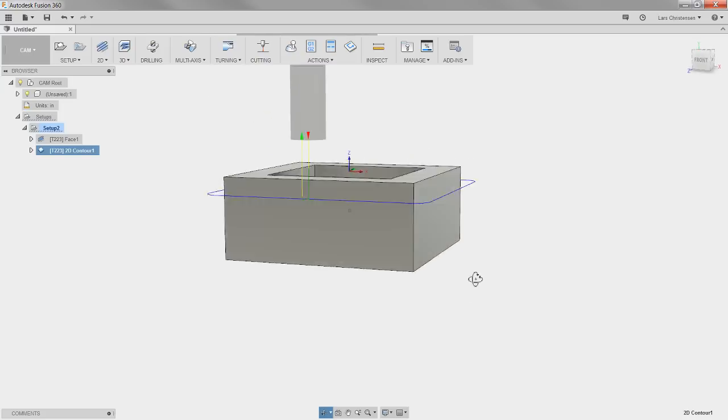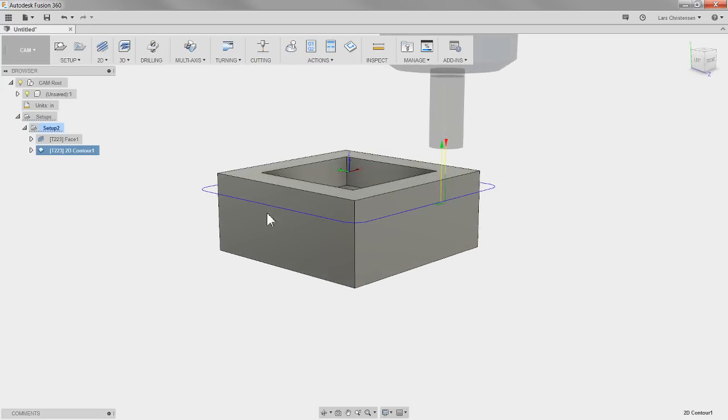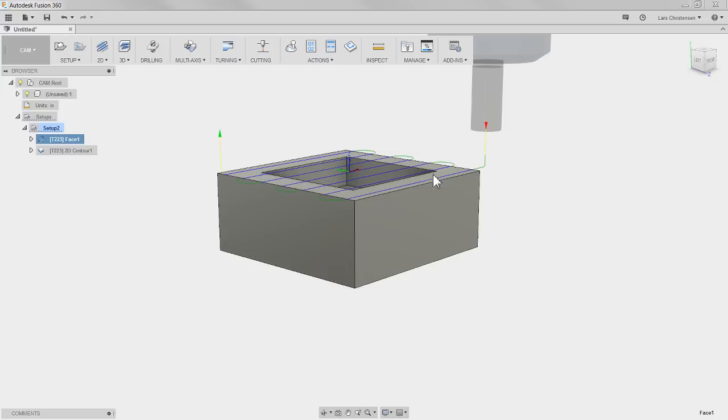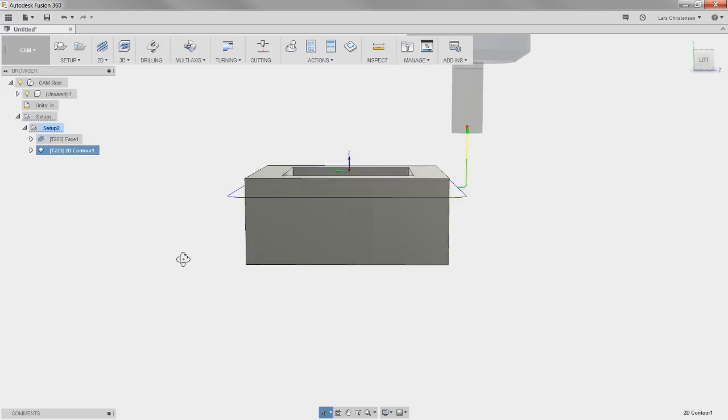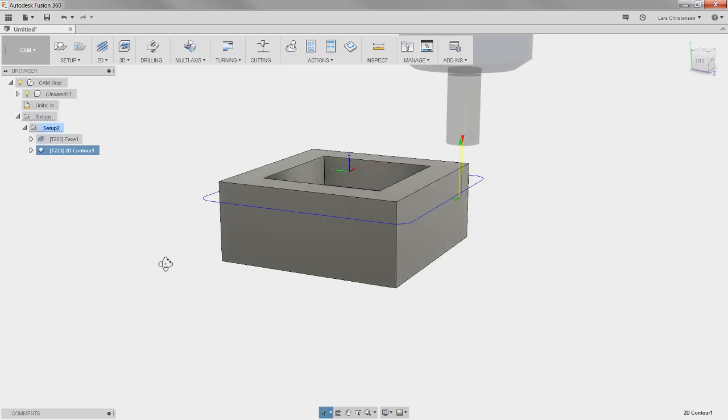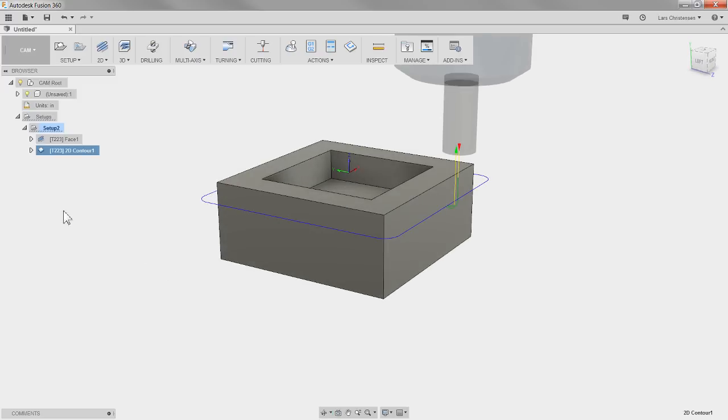That means that our cutter, and we're using the same tool we did with the facing operation, and the facing operation just barely touched anything, should only be 0.25 deep, okay? That means that when you are verifying this on your control, you should see that it's only going down to 50.